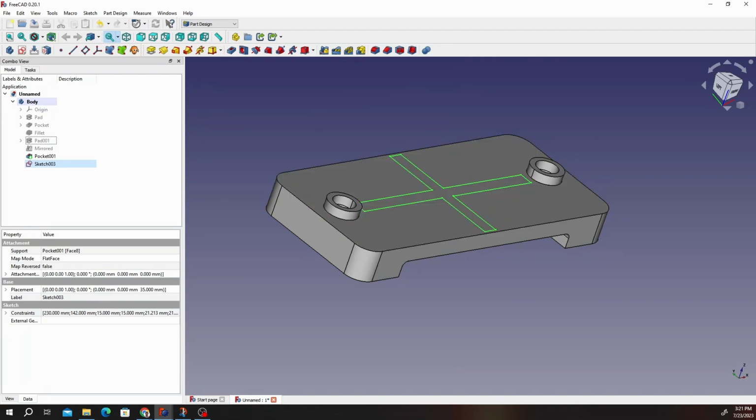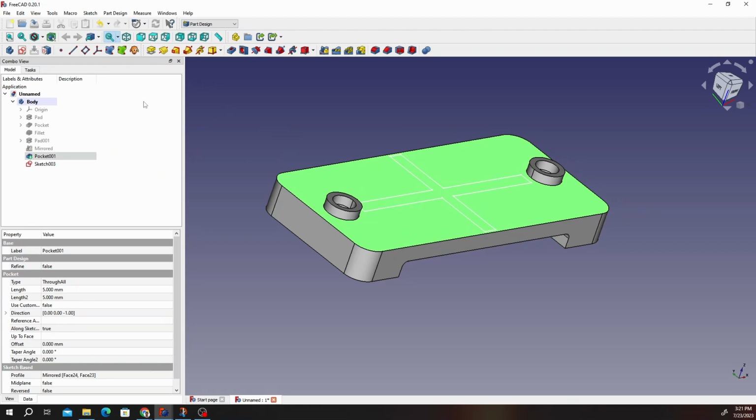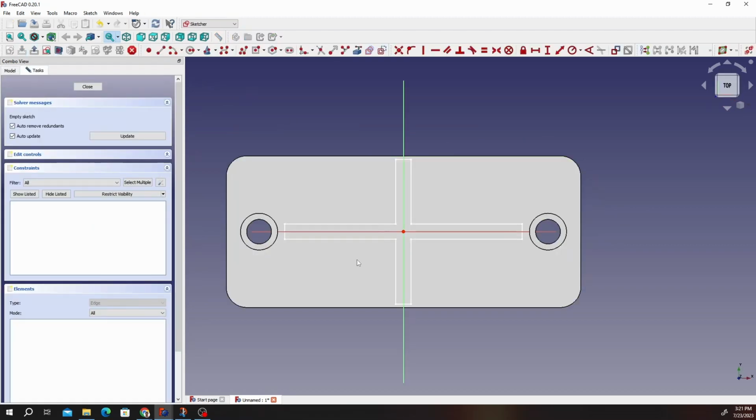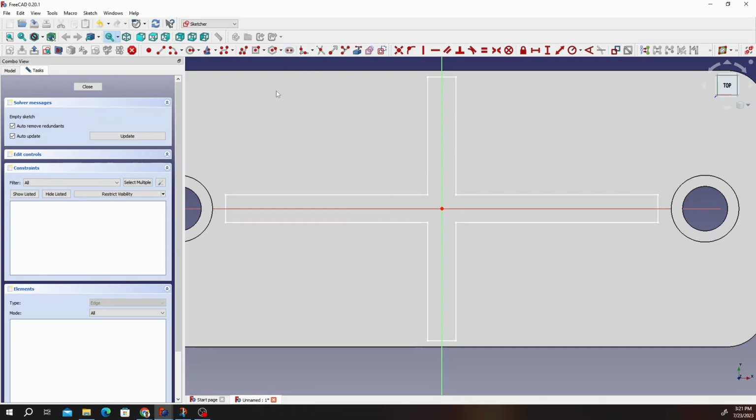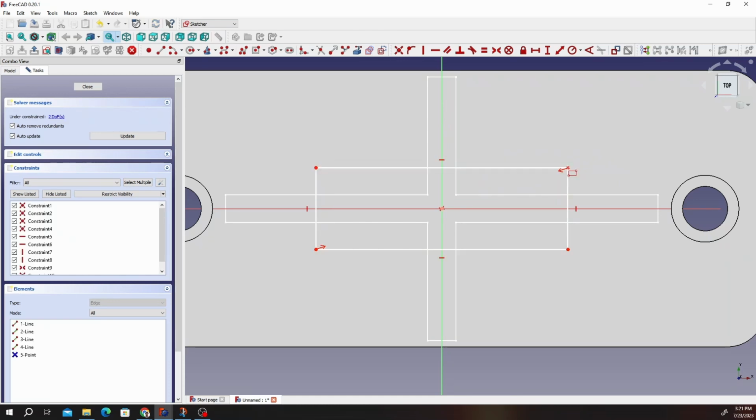And what we're going to do is we're going to create another sketch. Okay. And that's going to be on top of this face again. So click on that face and click on sketch. And then we're going to draw other squares again. So go ahead and click on that. Click on that. Like that. Basically, we're doing the same process. Hopefully this time we can constrain it faster.